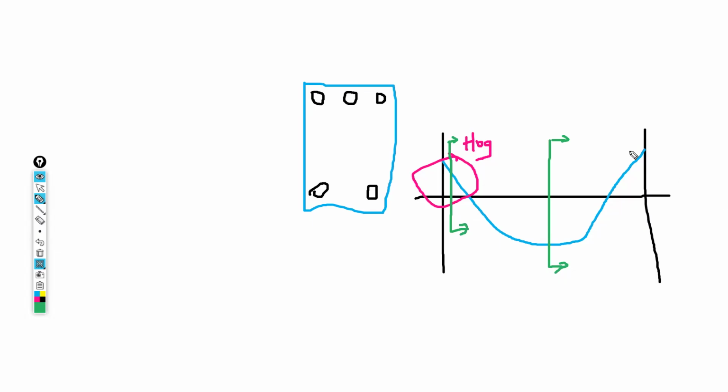So the loading at this point and at this point can be different. Therefore, also this section can change. You get it? So it is very important in your details, beam elevation details, to show those changes where you have additional reinforcements, basically at the support and also mid-span.